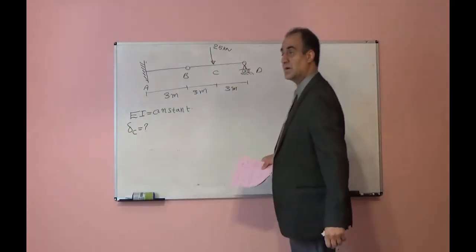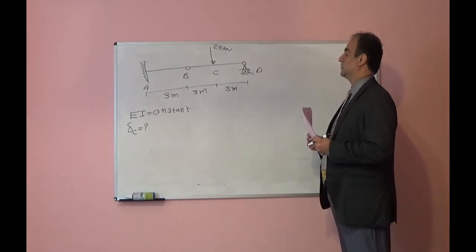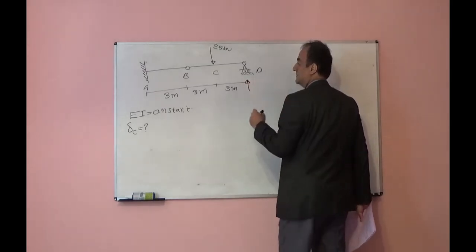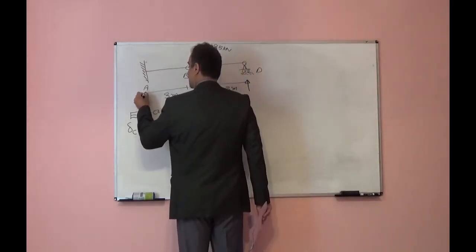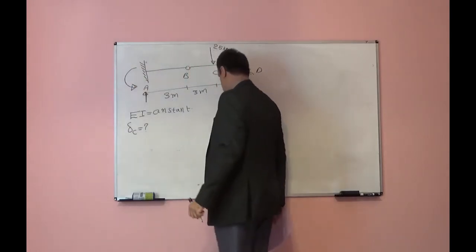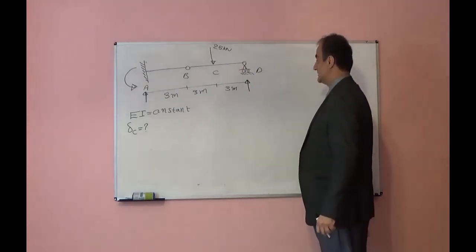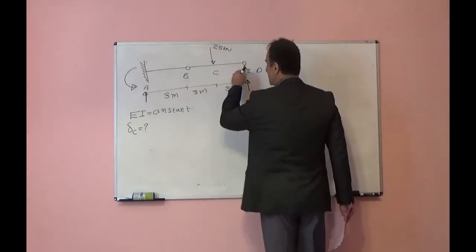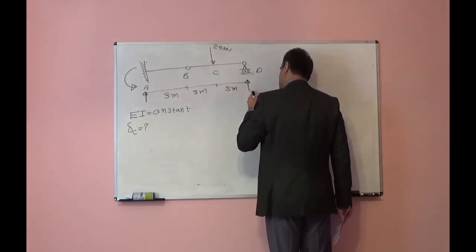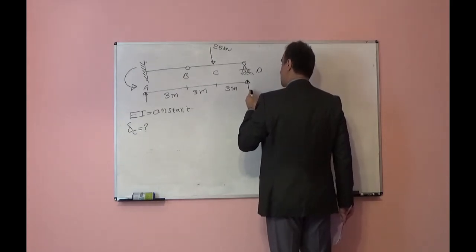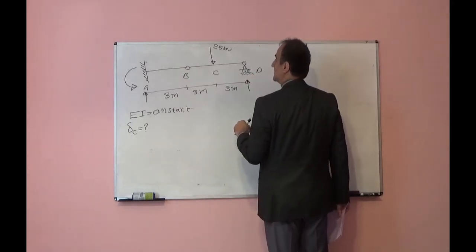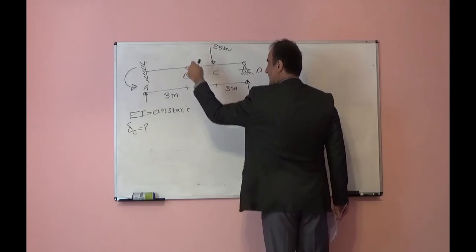First step, we should find the moment diagram. In order to find the moment diagram, we need reactions. We should find dy, we should find ay, and we should find ma, and we know AX is equal to 0. dy is very simple to find because the BD part is like a simply supported beam with 25 at midspan, so 12.5 will be the contribution of support D, 12.5 will be the contribution of part B.